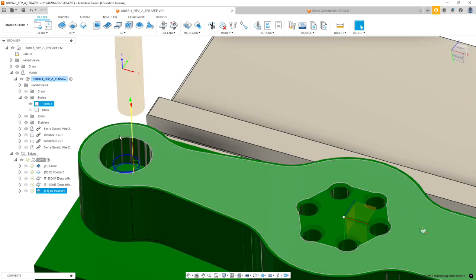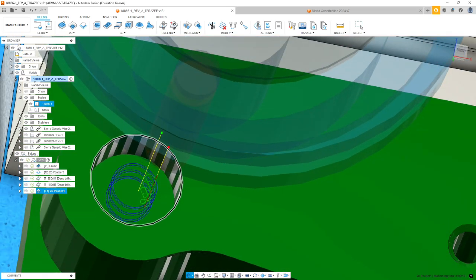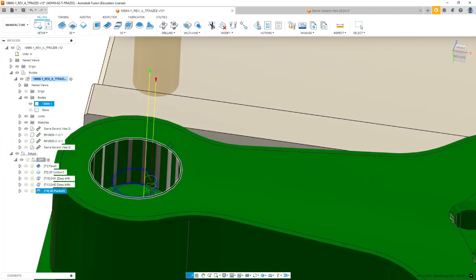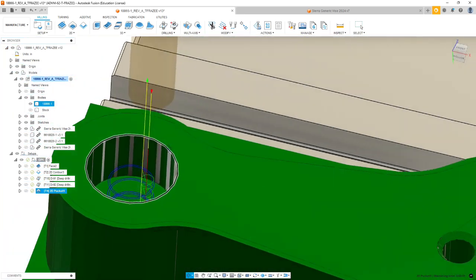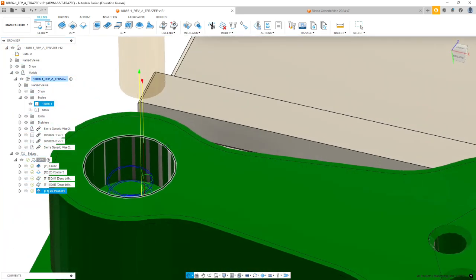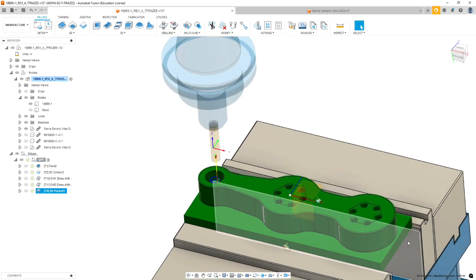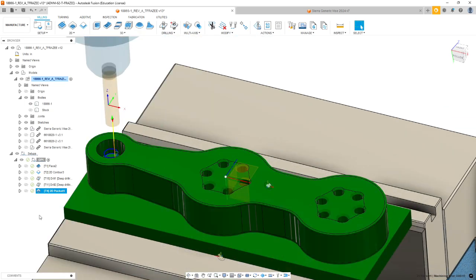All right. So it's going around one rough cut, one finish cut every step. Okay, because this is tight tolerance, we do want to do finish on each step. All right, now let's go into our hexes.